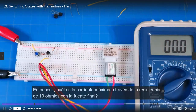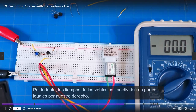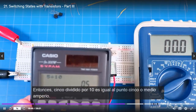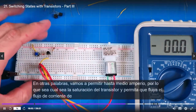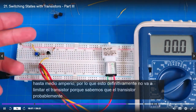So what's the maximum current through the 10 ohm resistor with a 5 volt source? So V equals I times R, I equals V divided by R, right? So that's 5 divided by 10 equals 0.5, or half an amp. In other words, we're going to allow up to half an amp. So whatever the transistor saturates at and allows for current flow, up to a half amp will flow.